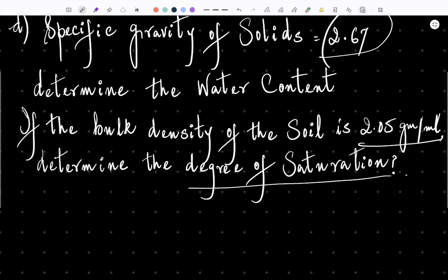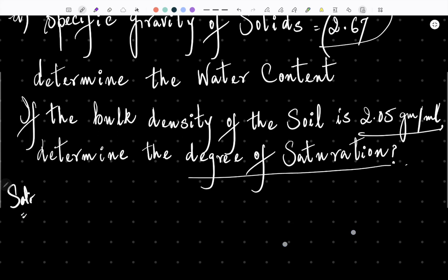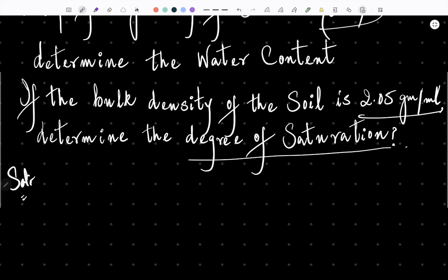All right, so let's do this question. This is a typical question for the determination of water content by a pycnometer. As you know, a pycnometer is a glass jar of about 1 liter capacity, fitted with a brass conical cap by means of a screw type cover, and this cap has a small hole of about 6 mm diameter at its very apex. Or also we can use the same pycnometer for finding out the specific gravity, but